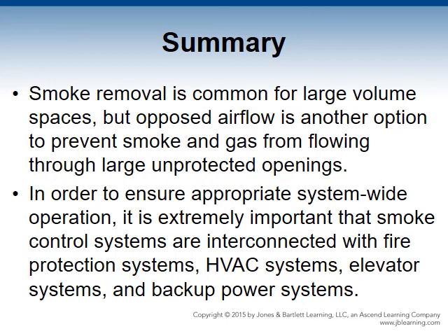Smoke removal is common for large volume spaces, but opposed airflow is another option to prevent smoke and gas from flowing through large unprotected openings. In order to ensure appropriate system-wide operation, it is extremely important that smoke control systems are interconnected with the fire protection systems, HVAC systems, elevator systems, and backup power systems.